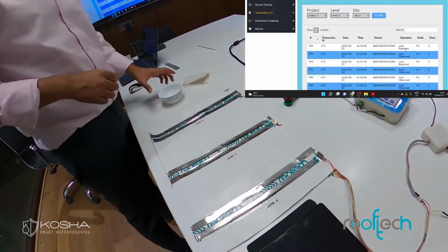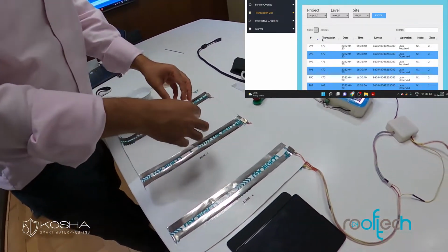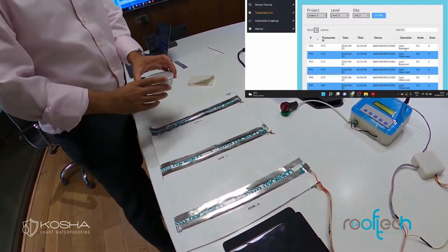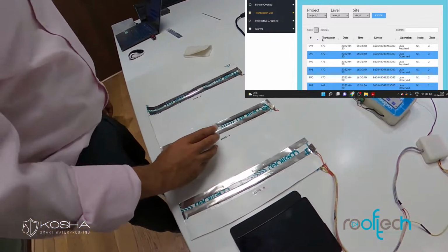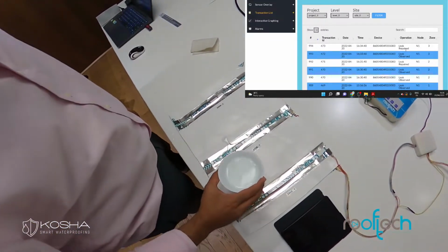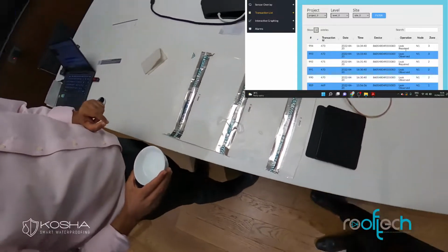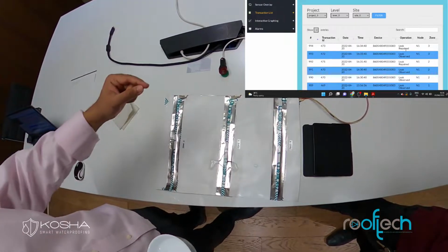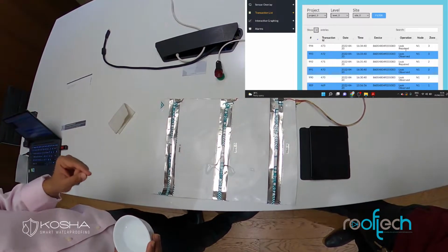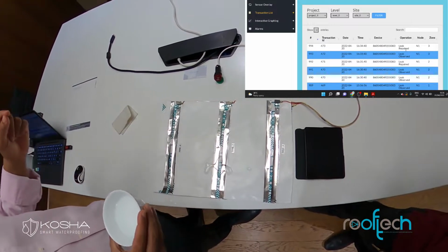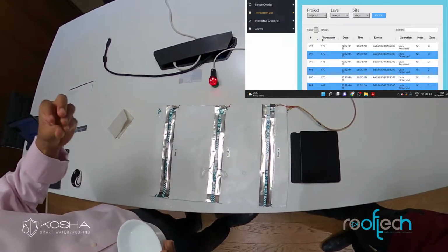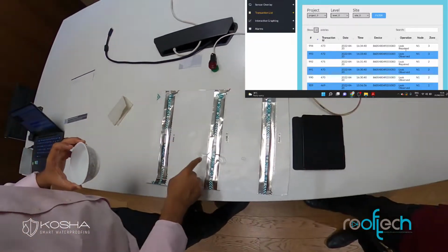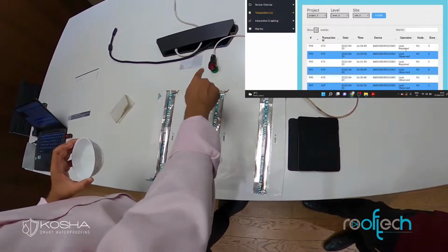Say a malfunction was near zone number 3 and water started leaking. That zone number 3 will be triggered. Once it registers, there is a 60-second delay because you don't want any false reading. If it outlays any of the ground connection, you don't want it immediately triggered. Once the leak is sustained for at least 60 seconds, it registers a leak.